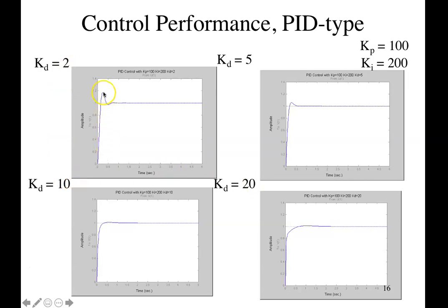You can see how the overshoot is reduced, from just under 20%, to perhaps a little over 5%, and then almost hardly any. That's probably quite a good response. If you increase a bit further, then the settling time tends to increase a bit. The rise time is okay, but the settling time takes a little bit of time to suppress that overshoot altogether.